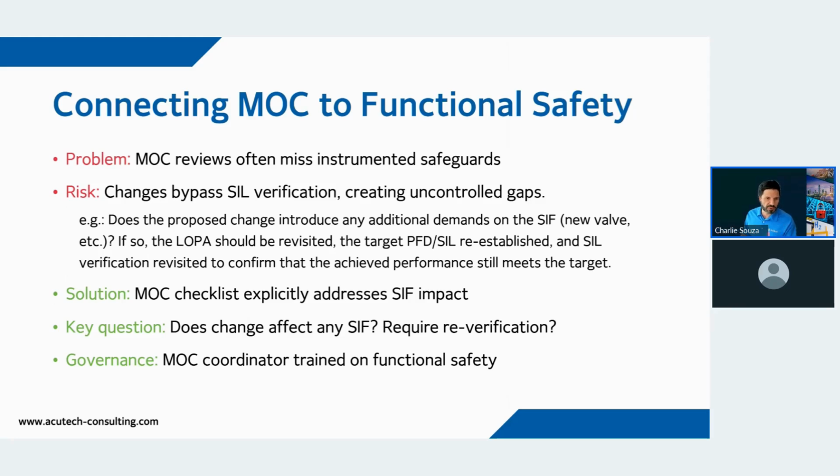One example here, a colleague of mine provided me, is: does the proposed change introduce any additional demands on the SIF? If so, the LOPA should be revisited. The target should be reestablished, the SIL target, and the SIL verification revisited to confirm that the achieved performance still meets target.